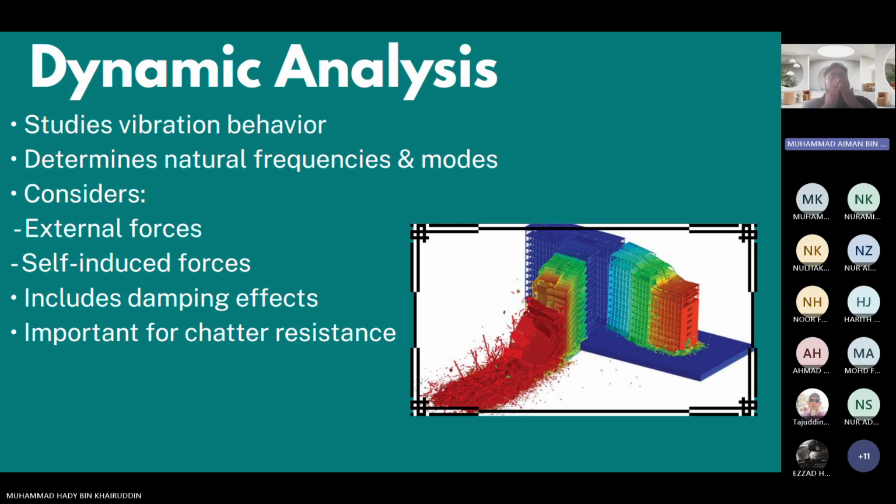Dynamic analysis studies time-dependent behavior, especially vibration. Vibration causes a lot of wear because of the movement, so we need to look at this even further using dynamic analysis. It will look at natural frequency, mode shapes, and even resistance to chatter.